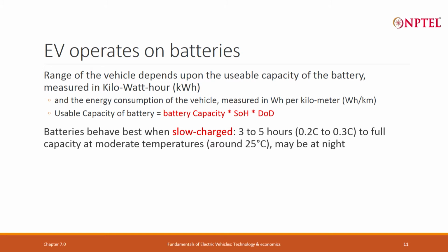And remember, this can be a problem, because you may have to operate at a very high temperature. So, generally, night time charging is considered quite good, because in India, night time gets cooler and temperatures will be closer to 25 degrees centigrade. It will be just the opposite in the West.